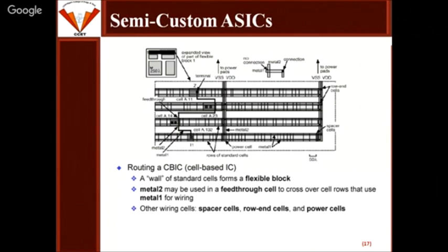Can you tell me why this is so? Suppose you have to make a hard disk, which is a memory device, and another is a microprocessor. In a microprocessor, we require a much higher number of layers, while in memories, we may not, because we are replicating the same thing. Yes, that is the point. In memory, basically, we create one type of block and then replicate it and make the interconnection. So we may require fewer metal layers to create the whole interconnection.